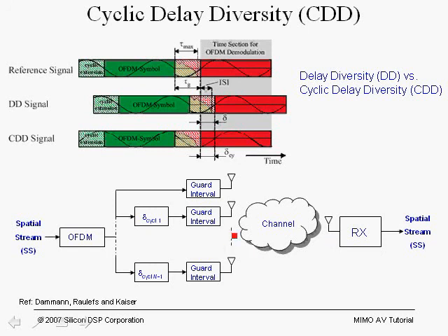And notice that the signal from this transmit antenna is delayed compared to the first transmit antenna and goes through the channel. When it is combined at the receiver, it is just like a delayed multipath, and the equalizer in the OFDM receiver will estimate and eliminate that distortion.